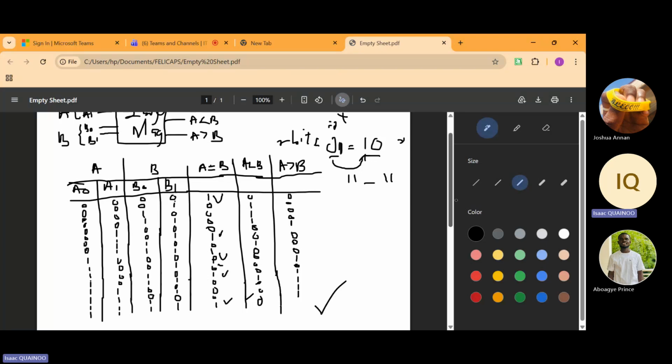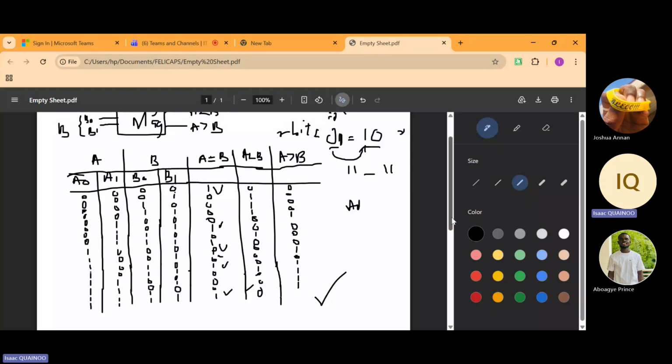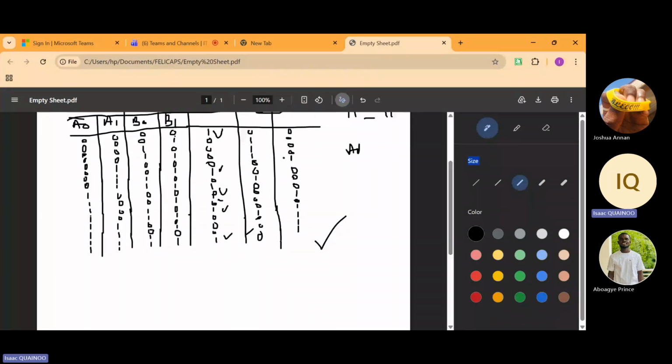So here, because the ones are quite a lot, you cannot take the A, B, C, D combinations, because you are going to have a whole lot of lengthy, complex equation, okay? So what you do is that you use a K-map directly to perform the minimization. So you separate this into, let's say, two groups of 8, and then you draw a 4x4 K-map.